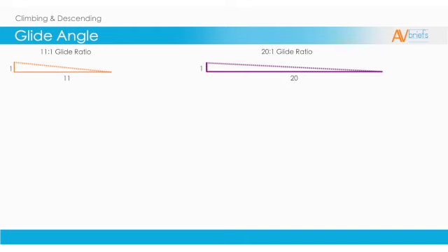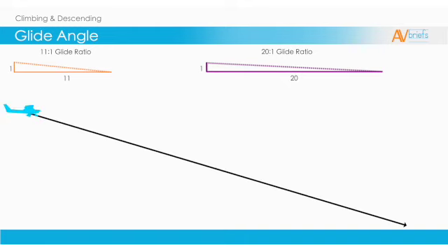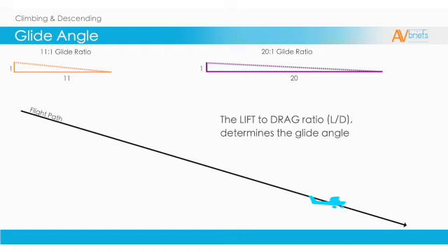The lift-to-drag ratio determines the glide angle. So the only two things which can affect the glide angle are lift and drag. Once the best glide speed, or best glide angle are achieved, there is no way of increasing lift, or reducing drag. Any change from the best angle or speed is negative to performance. Remember, the angle of attack is what sets the best glide performance. But as it is expensive to have an angle of attack meter in light aircraft, the angle is converted into a speed. This is fairly accurate.